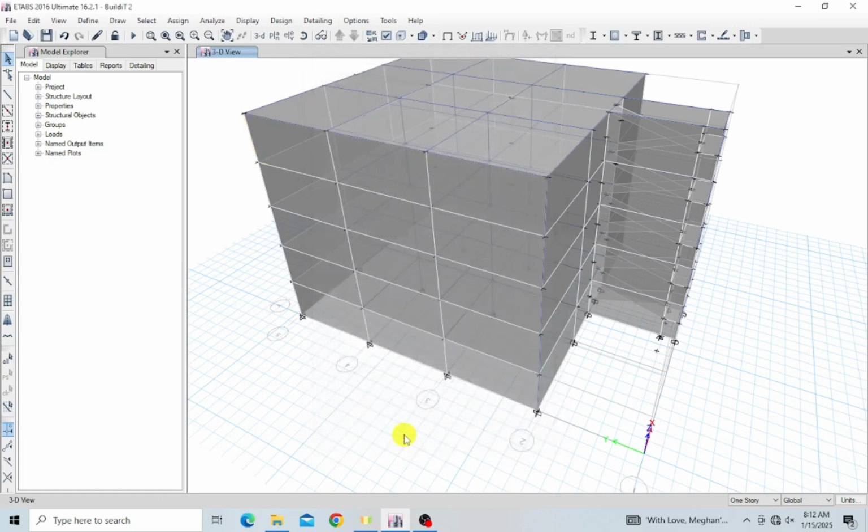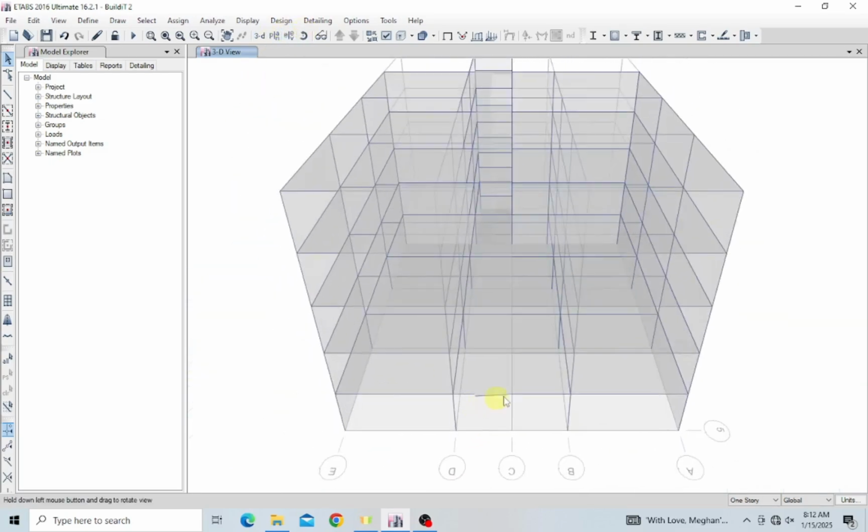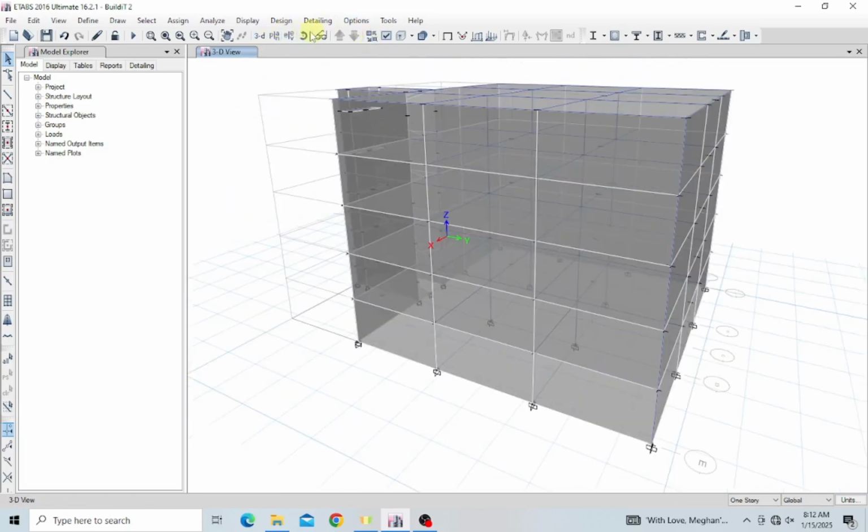It's just there to facilitate the distribution of the lateral loads onto the structure. So once I'm done assigning this cladding onto my structure, all I have to do now is to assign my wind coefficients. So I'm going to take you through how you're going to do that. Let's say we are assigning, as I said earlier, our wind X and our wind Y. So let's look at our global axis over here.